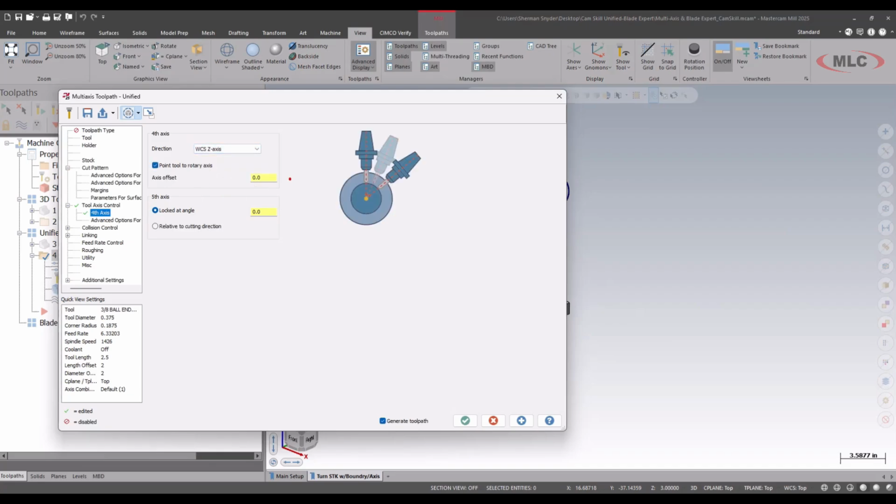We're going to point towards the rotary axis, but underneath this, we have the option to actually push our tool over to the side, as we can watch this little dialog to the right. You can see this option will push the tool to the right off the center. And then we have our other angle, which will tilt the tool at the given angle that we put in. I'll give it a 45 degree. Let's green check on this.